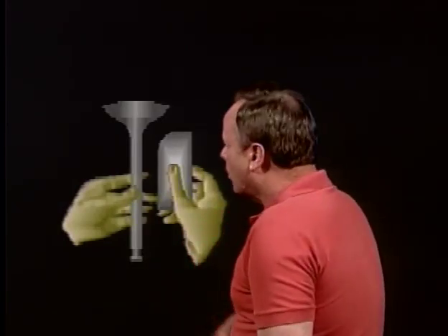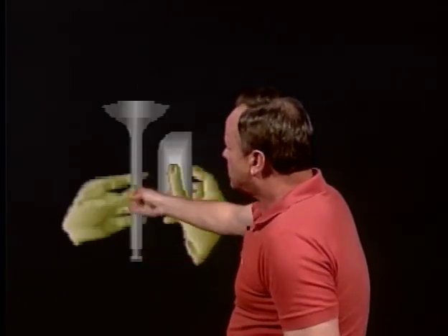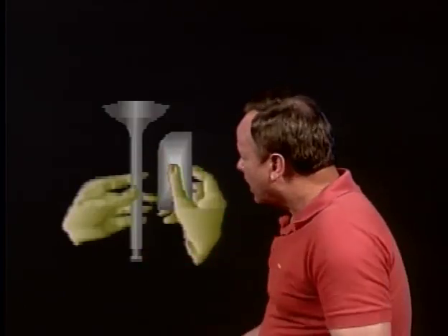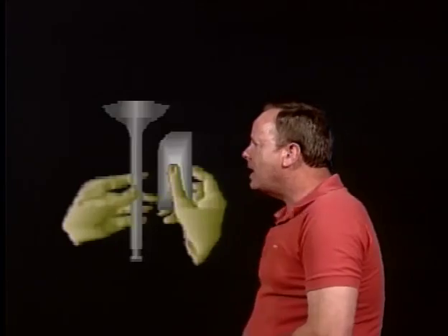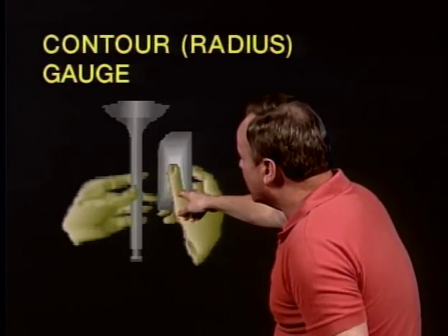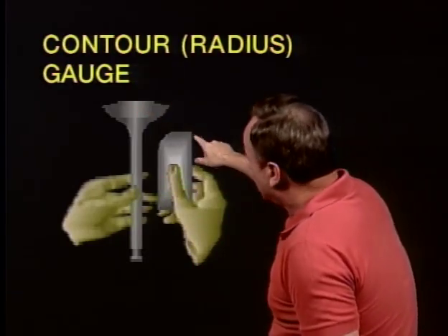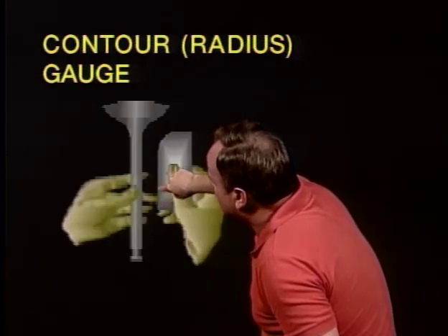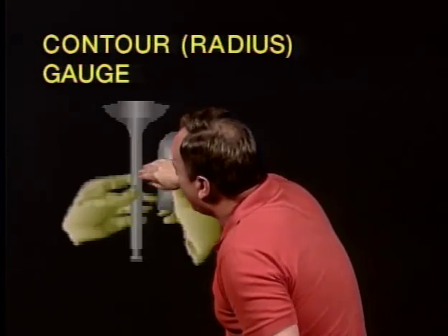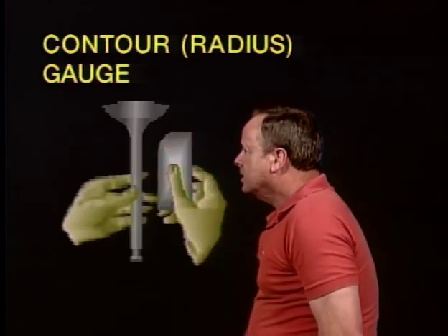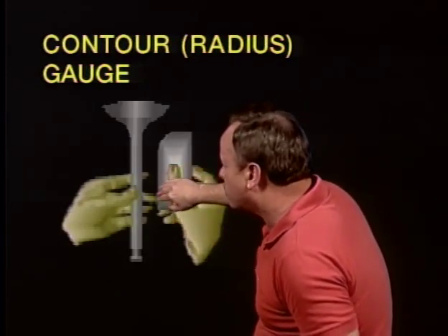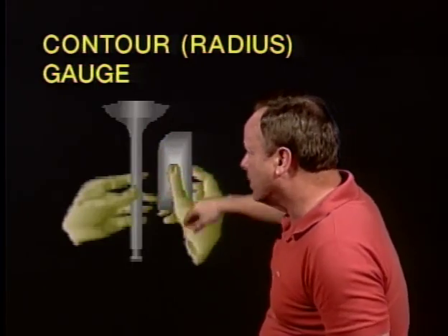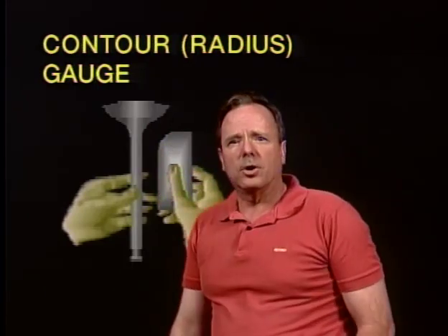So they're going to ask you, let's assume you're overhauling an engine, and you want to check to see if there's problems with this exhaust valve. Well, a couple problems you can have with the exhaust valve is that it can change its shape and it can stretch. Now, how do you measure for this? Exhaust valve stretch can be checked by using what is known as a contour or radius gauge, which is matched to the intended shape of the valve, and you see if the valve has its intended shape, and if it does, you're okay. So you'd find out if you had this stretch by visually comparing the curvature between the neck and the head of the valve and this contour gauge. It's generally supplied by the manufacturer. It's also called a radius gauge.